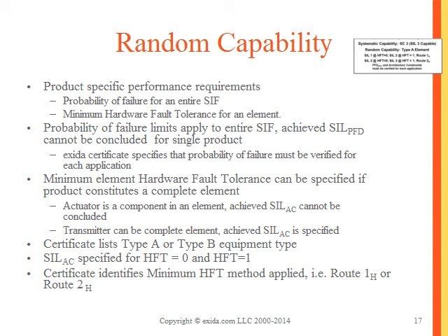That basically means for final elements, where the dominant failure mode tends to be dangerous and undetected, you need to increase the minimum hardware fault tolerance by 1, and you get that you need redundancy for SIL 1 applications. There's very few users that think that's reasonable, but that's what the standard concludes.